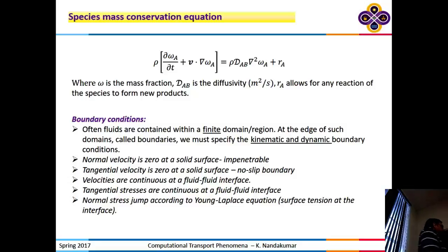But you can have a situation, and it happens in reality, and we can actually ask, how do I test this hypothesis? Let's take no slip as a hypothesis. How do we test it to see that it is real? That's a very valid question. So if I have flow in a pipe, if the Navier-Stokes equation is right, and the no slip condition is right, then I will predict a velocity profile that looks like this.